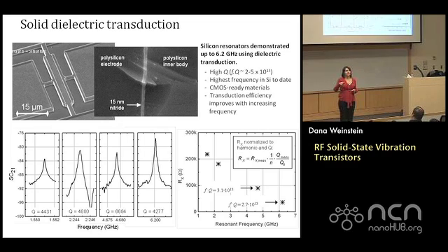And I'm going to have some peak, right, corresponding to the resonance. Well, the problem is as you scale to high frequency, the capacitive feed-through between drive and sense becomes such a problem that your signal is completely inundated by electrical feed-through. And so that's a big problem for scaling to high frequency using these passive devices.